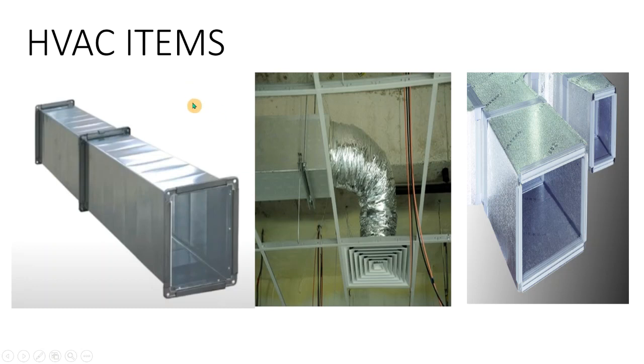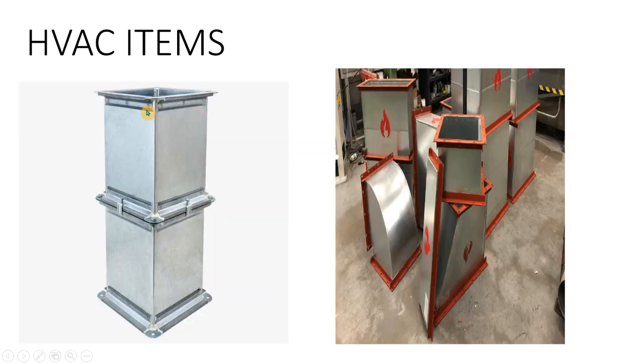HVAC quantity takeoff class. As you can see, we have two other ducts as well, which is the fire rated duct. Fire rated duct is majorly useful for car parking ventilation, staircase pressurization units, or in the basement. In these kinds of areas, we will be installing the fire rated duct. These ducts will not allow the fire to get out of the area of the duct. It can be coated with red color, or it's not mandatory to coat; it can be non-coated as well.